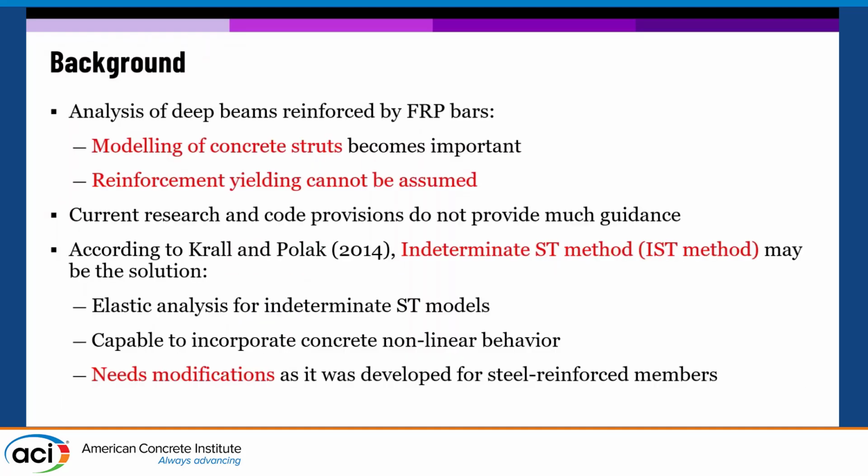I already said modeling of concrete struts becomes very important. If modeling of concrete struts is important, then also determining the sizes of struts, the sizes of nodes becomes very important when you have GFRP reinforcement in the strut-and-tie model.